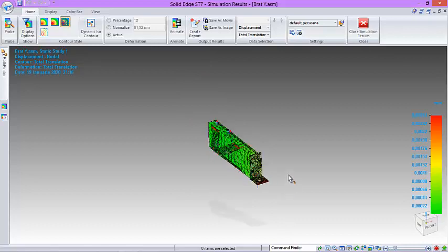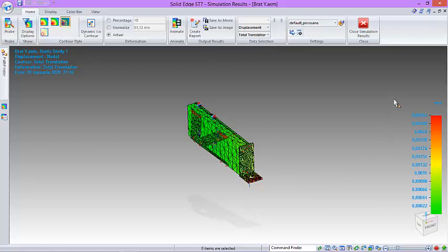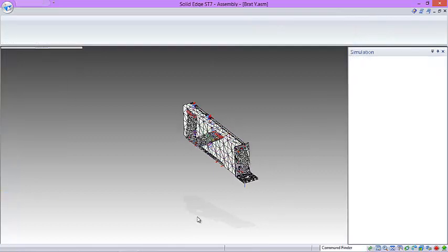In order to maintain the equipment within tolerance, I can see we're hitting the tolerance on the tip here. But if we think about it, we're applying 2 tons as if they were hanging due to gravity. So for such a small piece of equipment, I'd say it's good enough. So this component has passed the simulation as well.